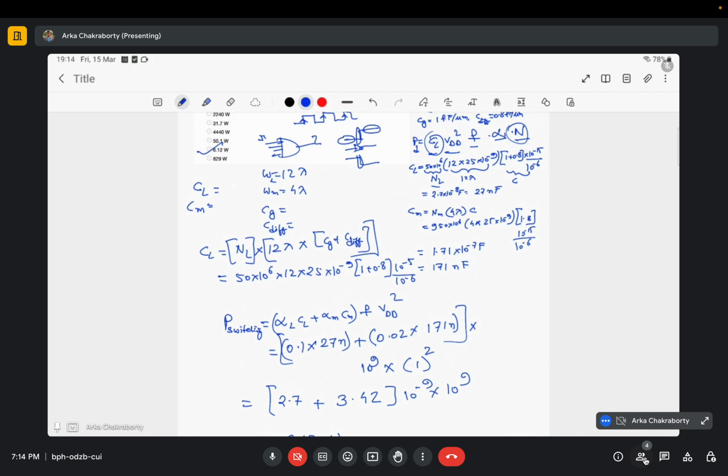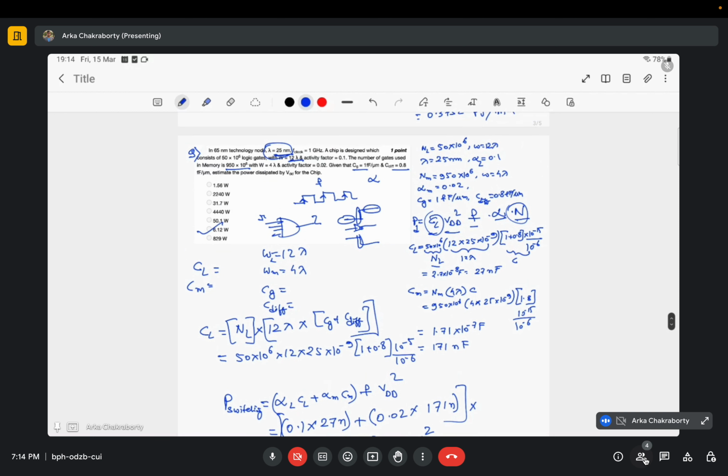For 180 nanometer, or maybe even 135 nanometer, you can say that. Below that, it is somewhere near 1 by 2 lambda, even at 65 nanometer, 45 nanometer technology. But around 20 nanometer or 16 nanometer, 22 nanometer or below, the name does not make any sense. Actually for 3 nanometer, lambda is something around 16, 18 or 20 nanometer. So to answer your question, you cannot directly say lambda is half of that. Is it clear?